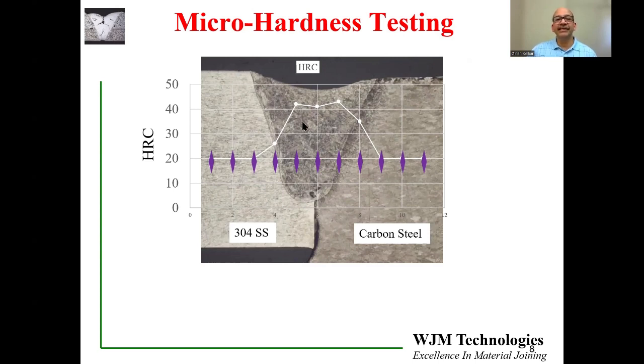How does it affect the analysis? A harder material is stronger, but at the same time it is also susceptible to crack growth. So, for example, this is a butt weld, and there is some unwelded region over here between the two components. If this particular butt weld was flexed, this point could have high stresses, and the high stress could initiate a crack.